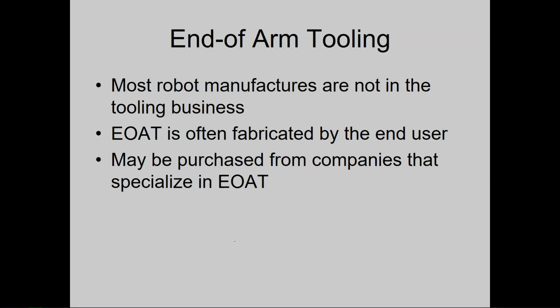Simply because the robot manufacturers focus on the robot itself. The tool, there's so many different ways and shapes, forms, fashions that usually if you're getting a tool, you don't turn to the manufacturer, you turn to somebody that specializes in creating these specific tools. Now, the bad thing about end of arm tools, and I will say this, you don't want to crash one, because end of arm tools can be quite expensive to replace, especially depending upon what kind you're using.